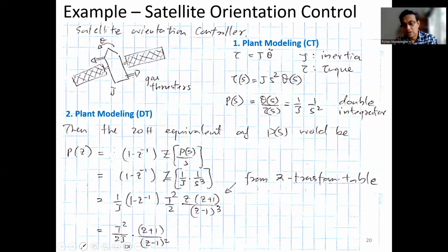So that's the basic principle of deadbeat. You want to cancel all the dynamics like an inverse dynamic controller. Okay, you have some dynamics in the plant, you have the exact inverse on the controller side, so they cancel each other. So input transfers to the output without any problem. Right.